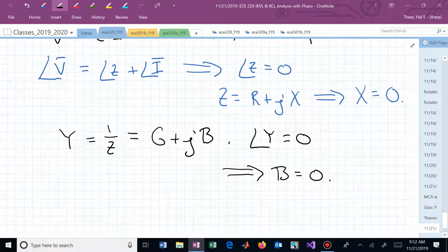We want the power company, no matter what we're doing over here with our motor, we haven't changed the motor. We still have a motor. It still has an impedance component, but we want to now attach across its terminals a capacitor so that now the power company over here, all it sees is what looks to be a resistor. Even though over here we have an impedance from the motor and an impedance from the capacitor, those two are playing locally and they're cooperating to actually look like they cancel each other out to the power company. That's the idea.